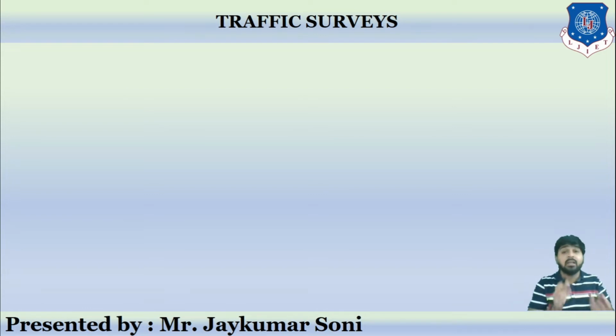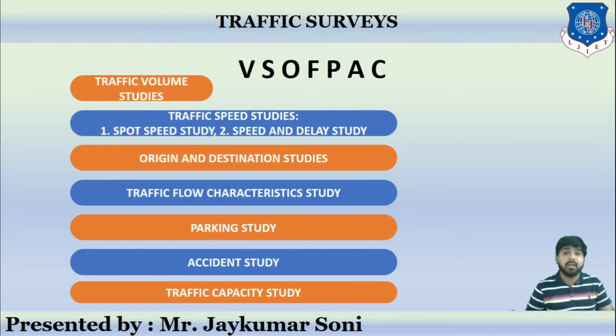As the name suggests, the surveys which are carried out in order to collect traffic data, in order to analyze the traffic, and in order to propose mitigation measures are called traffic surveys. These traffic surveys are of various types, and there is a shortcut through which you can remember them, called VSF OPAC, where V stands for traffic volume studies, S stands for traffic speed studies, O stands for origin and destination studies, F stands for traffic flow characteristic study, P stands for parking studies, A stands for accident studies, and C stands for traffic capacity study.